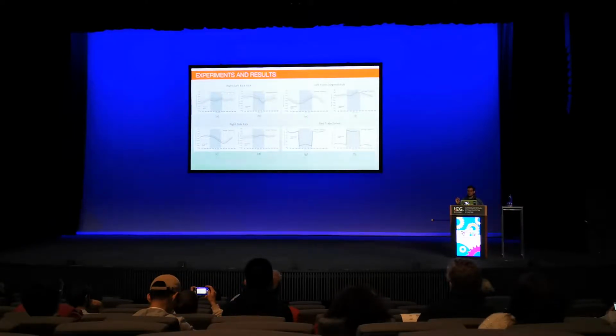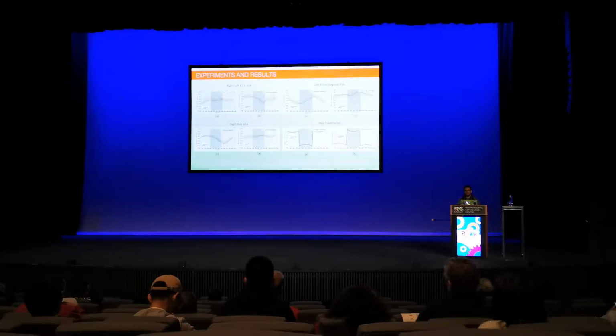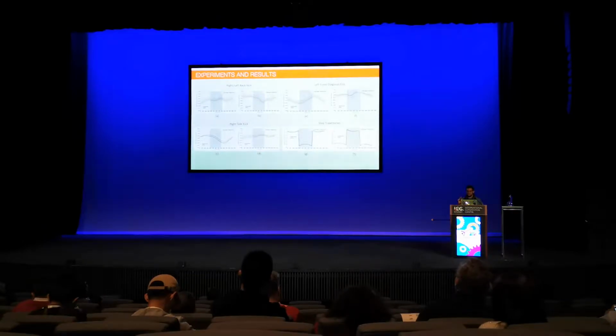And as can be seen in the graph, all the y-axis kick trajectories, as shown in figures C and E, moved as expected. As the robot kicks, the center of mass shifts on the positive y-axis in figure E, such as the left side, left front diagonal, and left back diagonal, because the swinging foot leaves the center of the robot, while also showing that the center of mass stays in the center of the support polygon. When the robot kicks in the negative y-axis in figure C, such as the right side, right front diagonal, and right back diagonal, the center of mass shifts towards the negative y-axis.